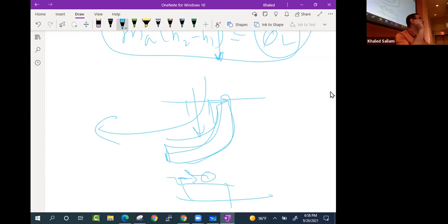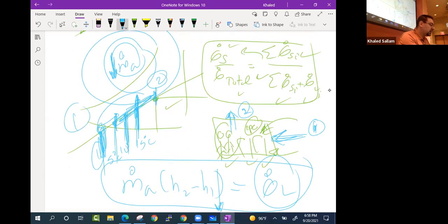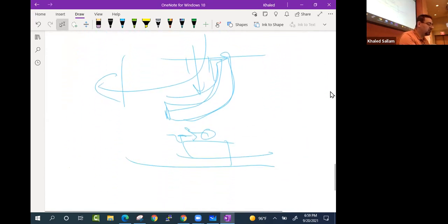The point is the air coming from the duct at 1 is not the good air. The exit from the room should be the good one, but the air coming from the duct is too cold to have on your skin. You need to diffuse it, mix it with the load, the heating from the sun, before you allow it to interact with the people in there. Okay, make sense? Right. So let's take a 5 minute break, and then we can go through the homework and the project. Okay, 5 minute break.